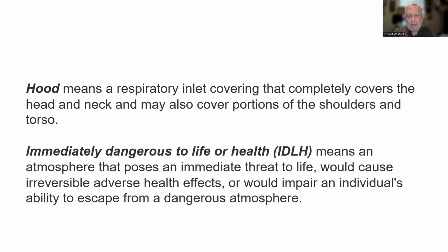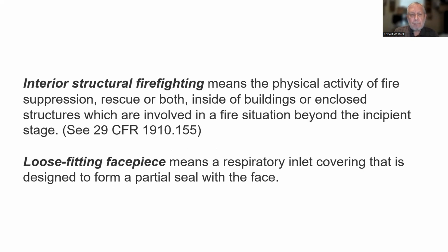Hood means a respiratory inlet covering that completely covers the head and neck and may also cover portions of the shoulders and torso. Immediately dangerous to life or health, IDLH, means an atmosphere that poses an immediate threat to life, would cause irreversible adverse health effects, or would impair an individual's ability to escape from a dangerous atmosphere. So it's any one of those. It says or, not and, so any one of those. In other words, it's immediate threat to life, irreversible adverse health effects, or inability to escape. So that's what IDLH means, not just dangerous to life and health.